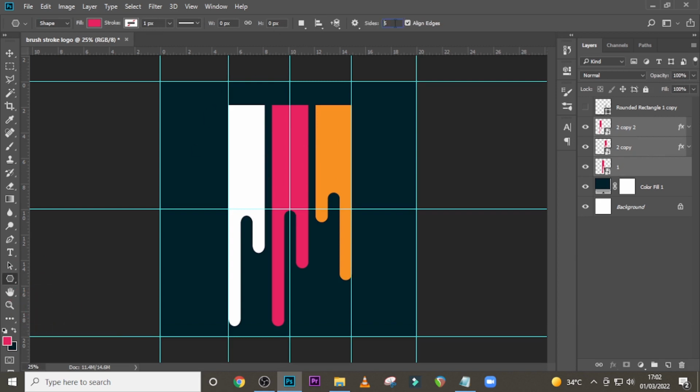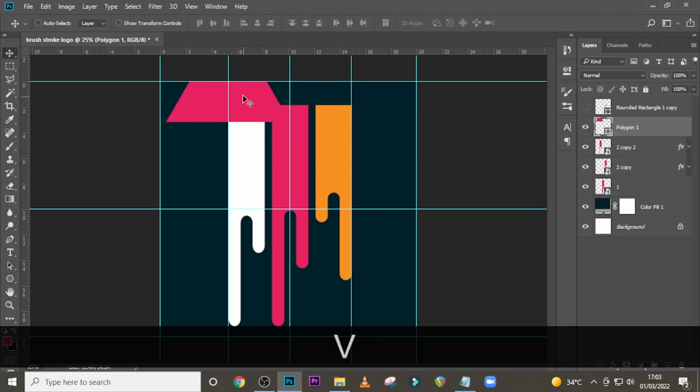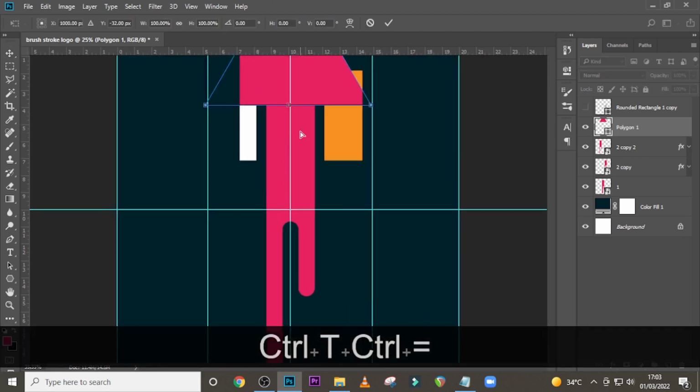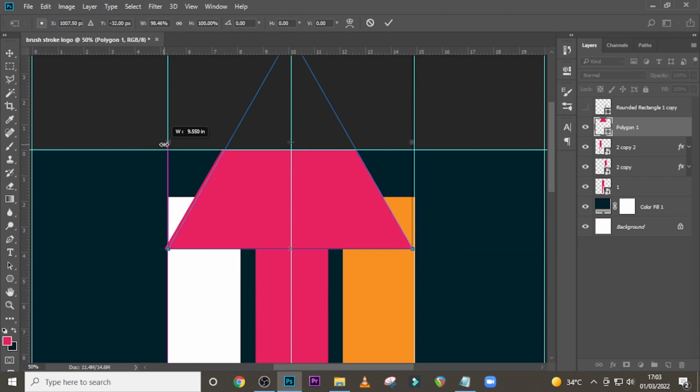And then close here, drag 1 2 3, click here, let's select this, let's select polygonal 2, and then let's change the size over here to 3, and then let's hold shift and then rotate it until you have it something like this. Great. Now drag it here until it touches both sides. You want to zoom in until it touches both sides.